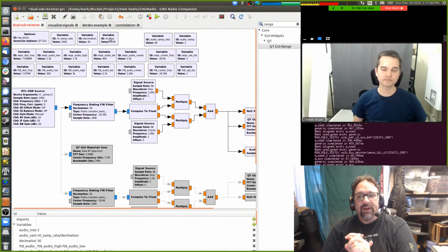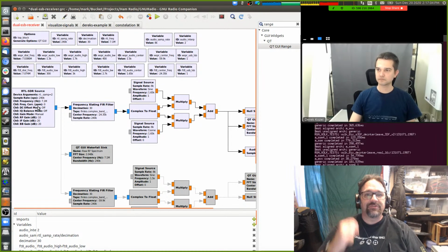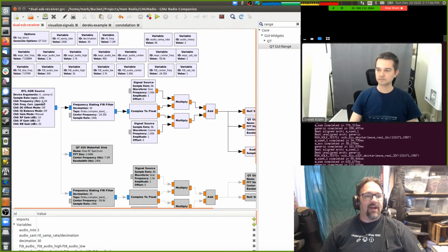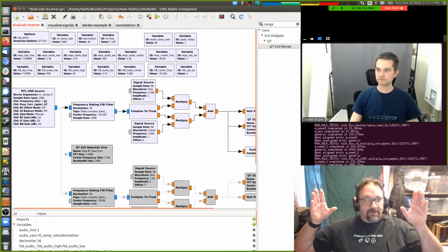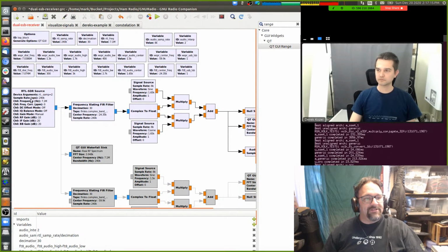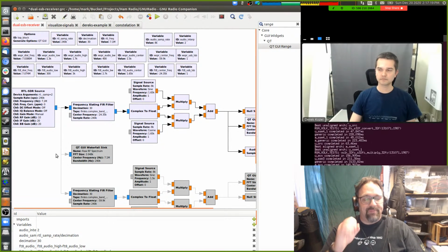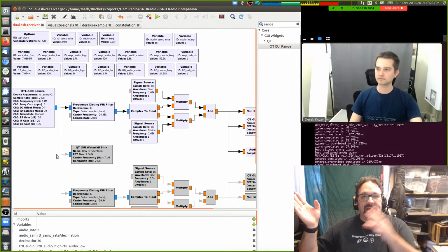So before it even comes out of the RTL-SDR block, we have already done those first components. So I've got the 7.1, we've got a pretty wide filter of 240 kilohertz, but it's all down at baseband. So the output of my RTL-SDR signal, this complex signal right here, is baseband 240 kilohertz wide, plus 120 minus 120.